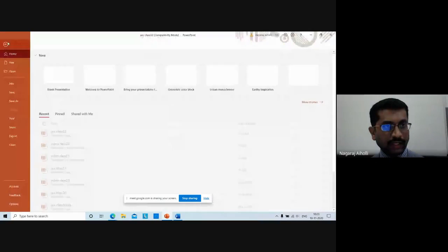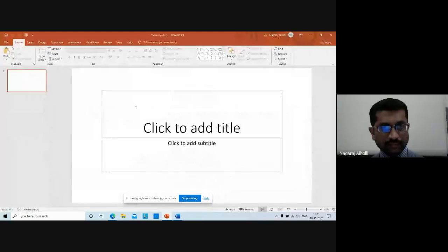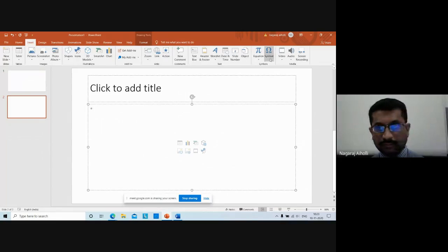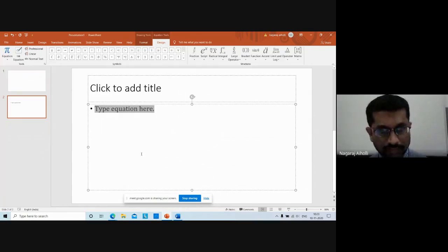Starting from VCC: VCC minus IB RB minus VBE minus IE RE is equal to 0.